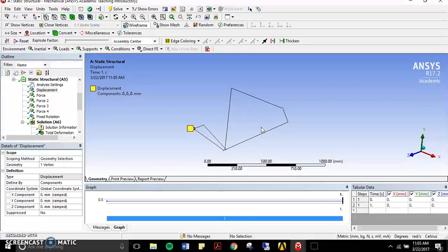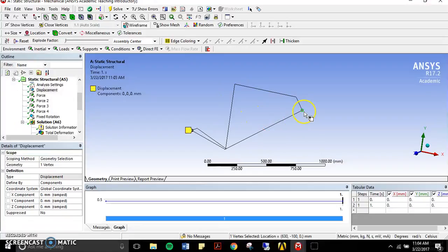So, for example, a displacement in the x direction shouldn't affect our analysis very much, because there's no big forces in the x direction, except I suppose for the acceleration, and perhaps from the mass being accelerated. So what we do is we fix it here in the x direction, or indeed at the handlebars, somewhere that it's going to interact with the front wheel. That way, any acceleration force from the rear wheel can be translated through the entire frame, and we can capture that quite nicely.